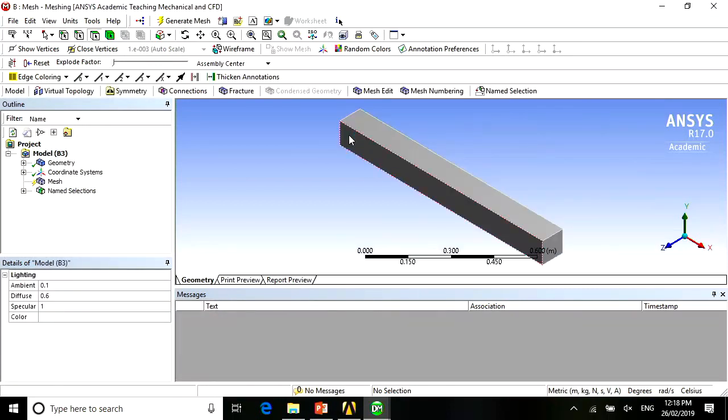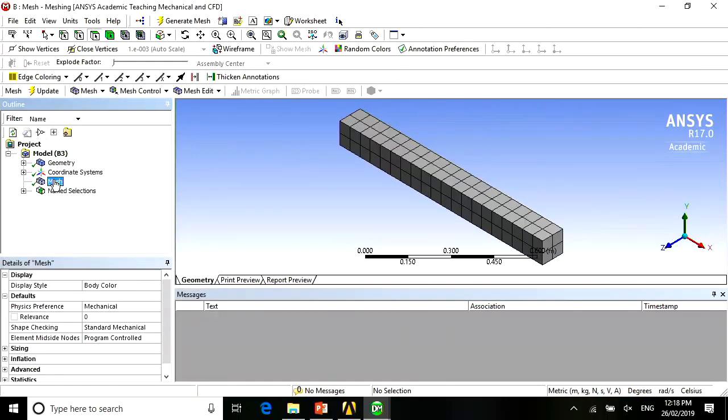Now, for argument's sake, I'm going to generate the mesh. I'm going to ask you a question. Okay? Is this a good mesh? Why? Huh? Too large, too coarse, right? Okay, you can see how many elements are there on the face? Only 4. Right? So you can just imagine that if you take the center of the element as where the flow is going to come out, you basically have 4 points, right?